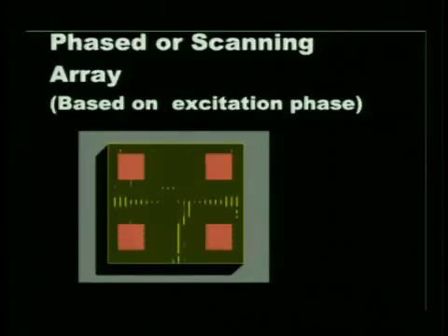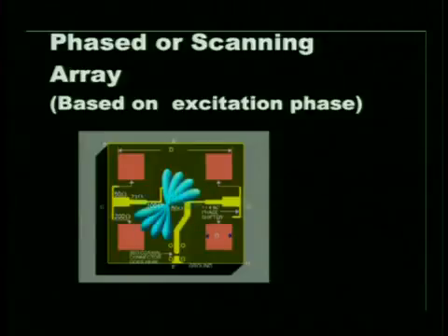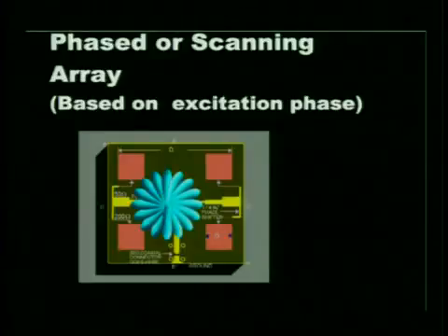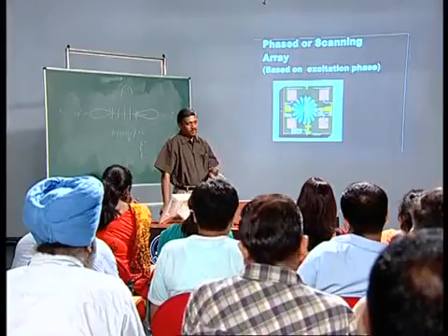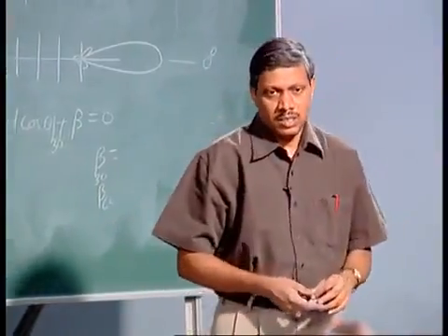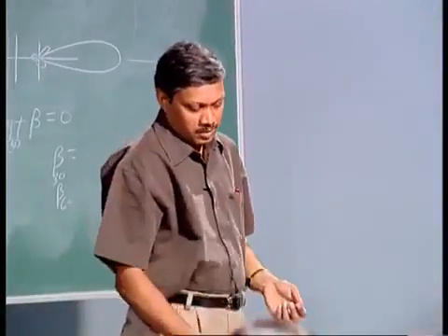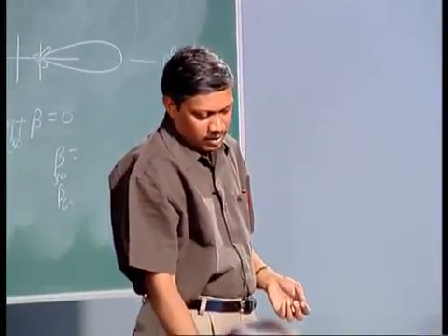So, these are the original slides which I had shown you. This is basically to give you an idea of a phase shift array. If you look, first it is generating in this direction, then gradually it is creating another direction, then another direction, like that you have a situation of scanning in different directions. So, the shifting is from 0, 90, 270, 180 and any other direction in between. Like that you will get a phase shift array. So, now how to attain this phase shifting?